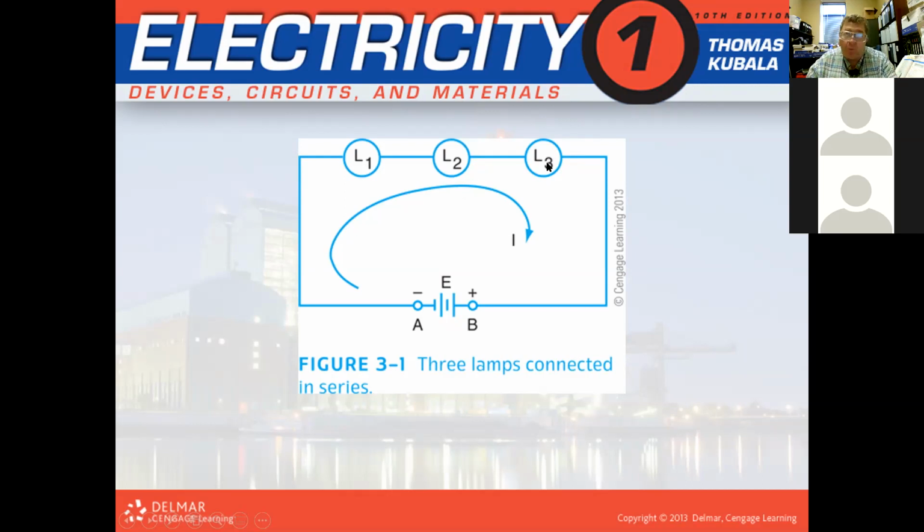That sounds strange, but we're going to do it when you're here so you can see that it actually works that way. When there's no amps flowing, wherever the break is in the circuit, when you go across that break, you're going to read something very close to the main power supply voltage. You have to really see it on the board to take it in and see that it really does work that way.